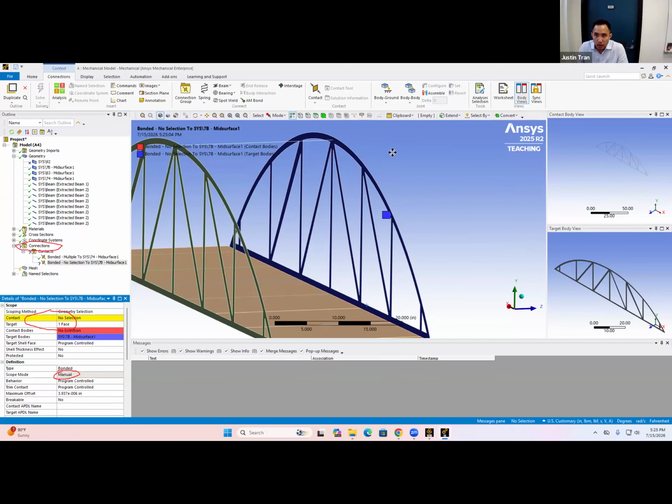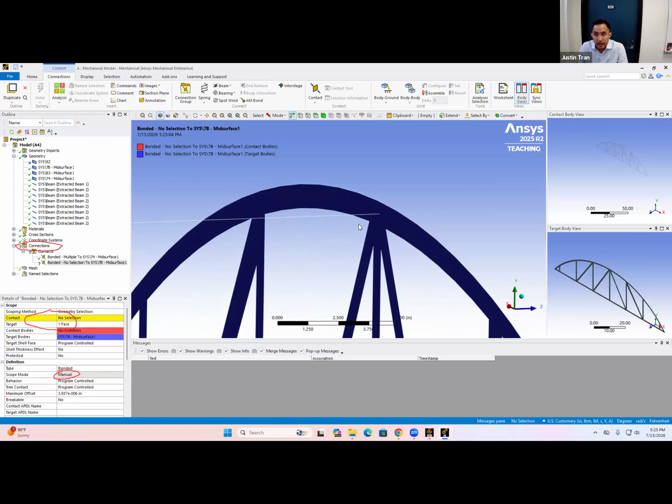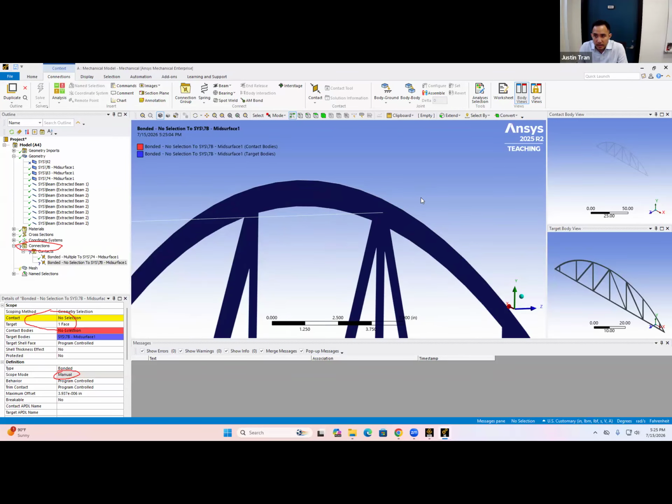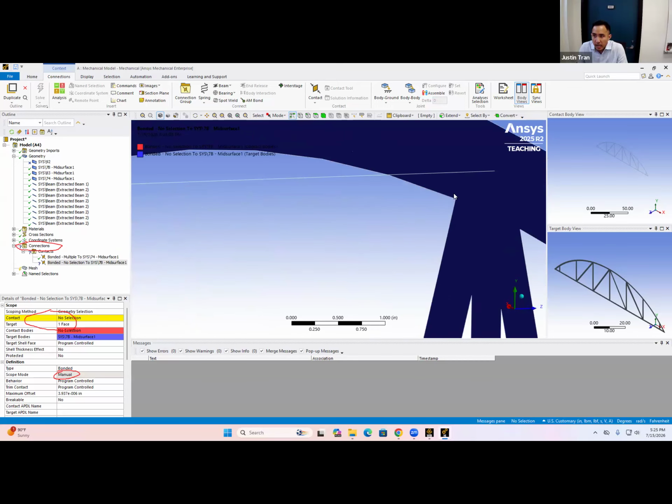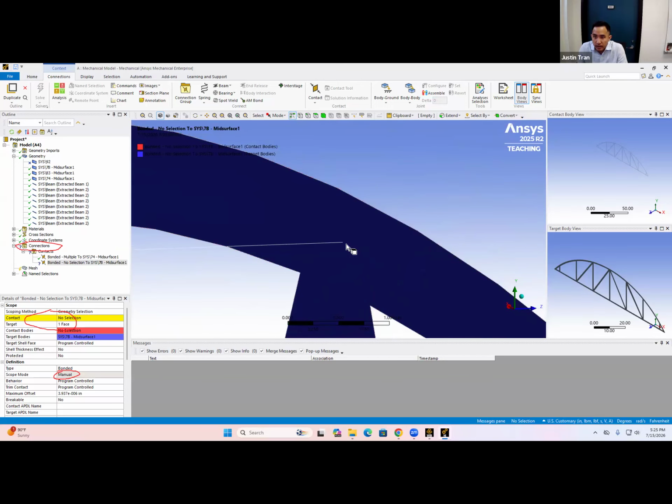And then we want to connect the beams to that bridge, but we only want to connect just the ends of the beams here, right? So there's one point right at the end of the beams. And it's very hard to click unless you zoom in. One thing that can help is that you can change the selection mode up here to vertex mode. That way your mouse is only going to snap to any points in the structure here.